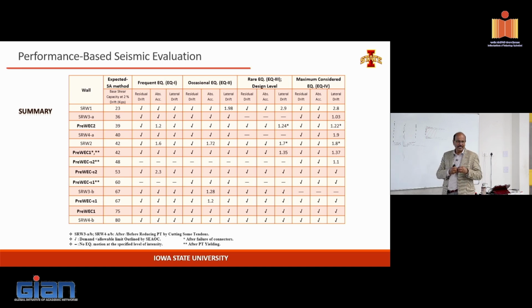But we did find that if you keep stretching it, so I don't know if you guys do strand testing in the lab. When you do it, how do you hold it at the ends? We put the regular anchorage, right? So if you put it, you never break the strand. You always break it at the end. So the same thing happens there, right? Because strand has a strain limit of 0.008 or whatever. You will never reach there because wedges cut into it faster.